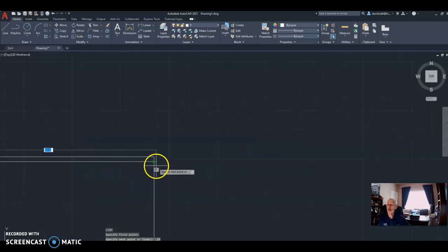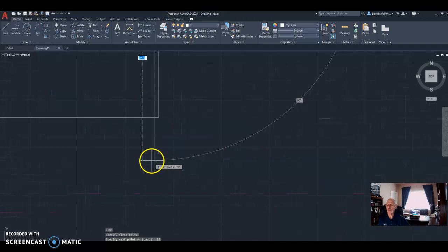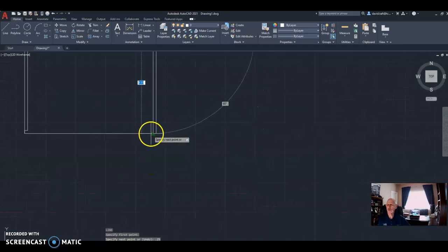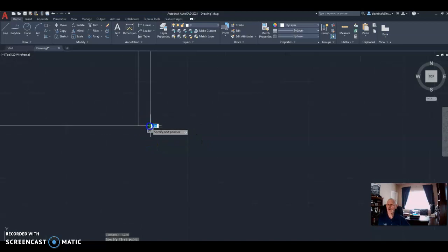And like I said, you can do the math on this if you want. The main thrust of this exercise is drawing lines and controlling lines by distances. Again, 0.25 from the corner, and come down with the snaps on. And again, I'm going to do one more here to complete the border.